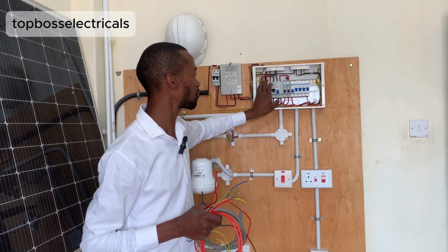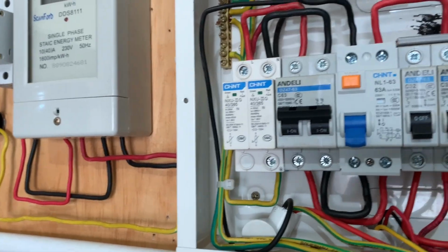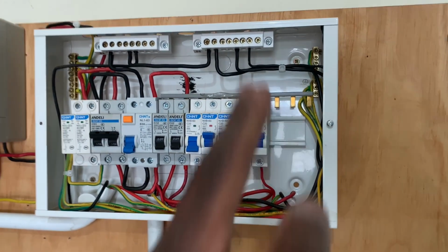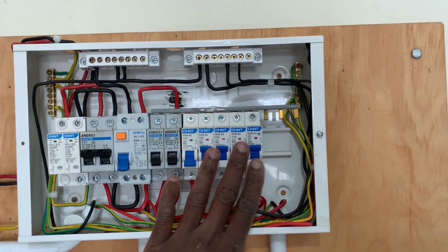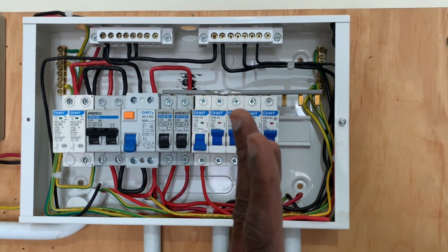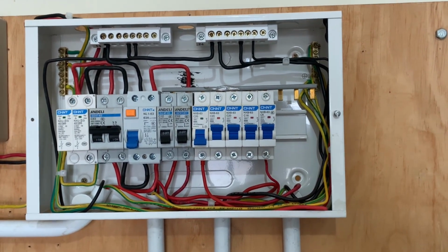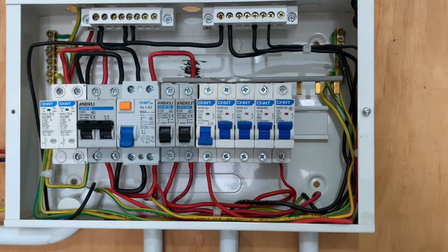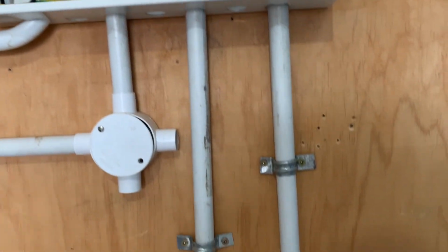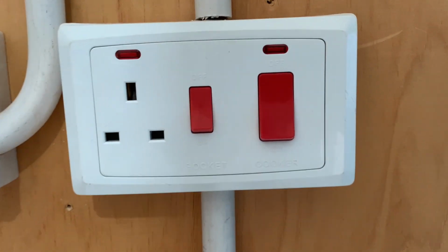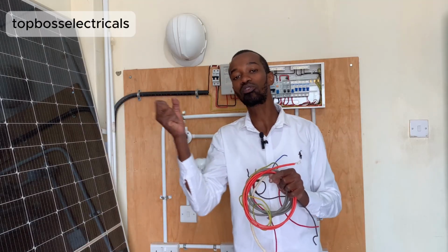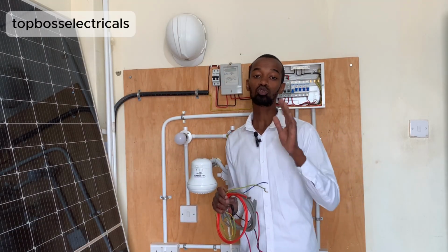Now, it is very important for you to note that it may drop to the consumer unit as a single circuit that is feeding the consumer unit, but just have a look at the multiple circuits that are connected from the consumer unit. Assuming that all of these loads will be on at the same time, it definitely means that the cable that is supplying power has to be of a bigger size than any of the cables connected in there. Why? So that it can be able to withstand the amount of current that is being drawn without overheating.